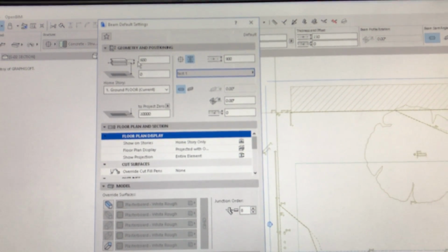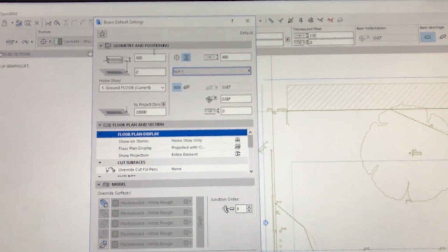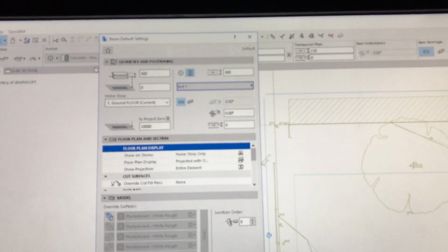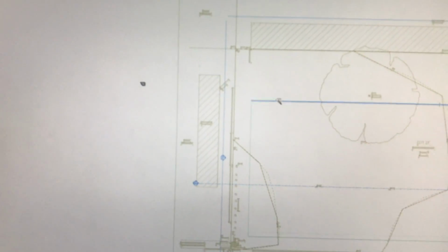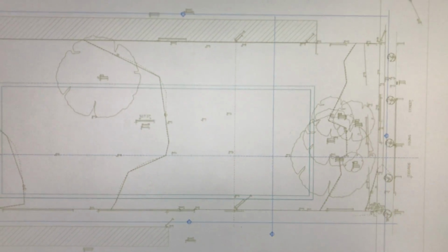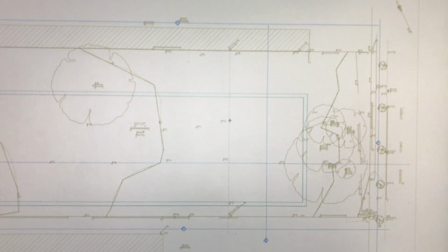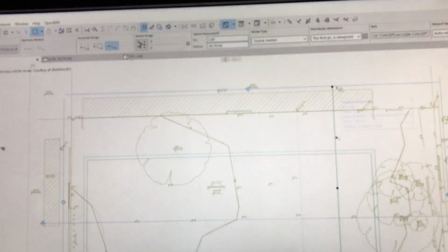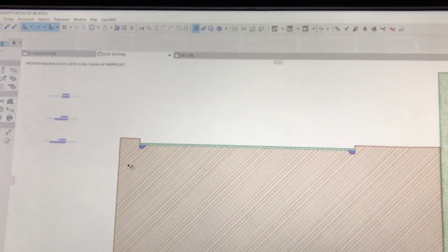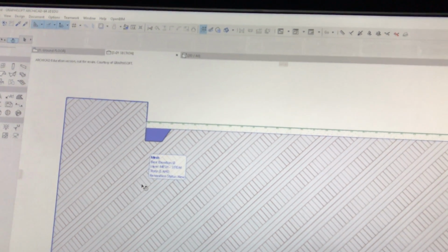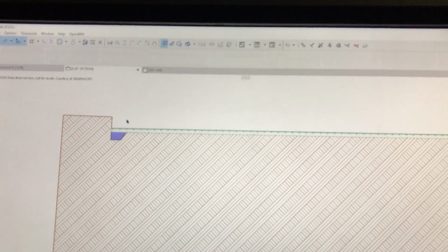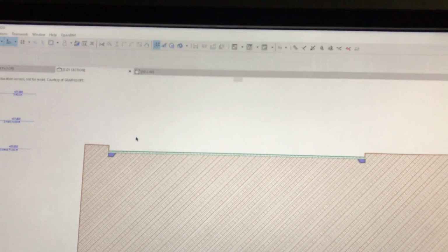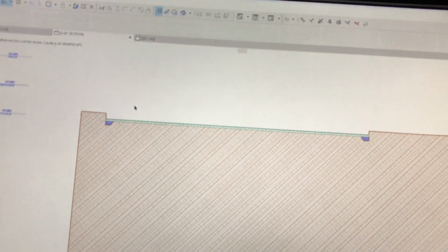And what I want to do is reinforce my slab around the edge with that type of footing. So I'm going to press OK, and I'm going to use the space bar, turning it into a magic wand, and bang, it's drawn that. It's probably in the wrong spot. Let's see in the section where that turned out. Let's fix it up later. Oops. Oh, went in the right spot. That's lucky. Okay, so there's our slab. There's our new footing that we've made. And we're starting to really build more like building elements now, instead of just bits of cardboard.